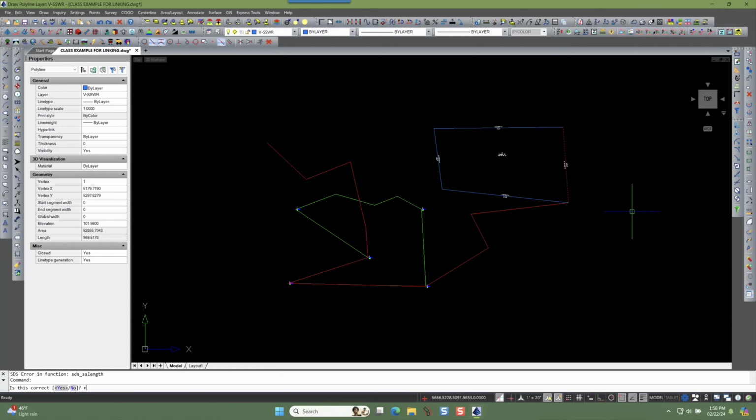And I could say no again and say, now it is correct. I'm going to say yes. And now I can just keep going and do various things. I can type a D for distance, and I can put them in meters, feet, chains, lengths, rods, or a pick. Let's just go with feet, which are in my angle brackets. I see those less than and greater than signs. So the distance will be, let's just go 100 feet.